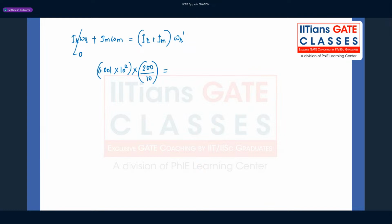Coming towards the right hand side, we have I_R, which is already given to us as 0.1. I_M we have just calculated: 0.001 into 10 squared. Okay, so it's like m r square basically, into omega_r dash. If we solve this omega_r dash, it will come around 10 radian per second. So the answer for this is 10 radian per second.